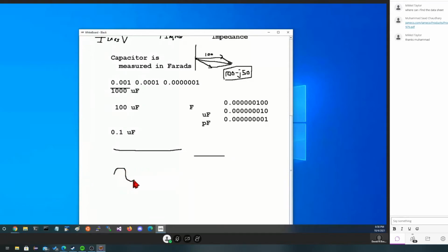If, however, we gave it a sine wave that's constantly changing, we're going to see something that looks like a sine wave on the other side of the capacitor, but it's going to be out of phase with the sine wave. Because while this is able to change, remember, voltage on the capacitor is slow to change. So if we were measuring the voltage we were applying, which is going to be basically a current, which should then change the thing, this looking like a sine could look like a cosine wave, for example, on the other side. We're not going to do the math to worry about what it will be.